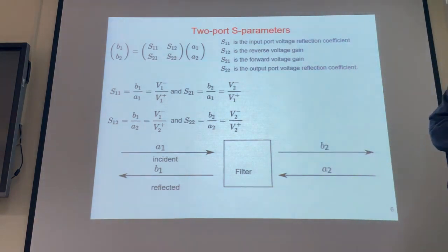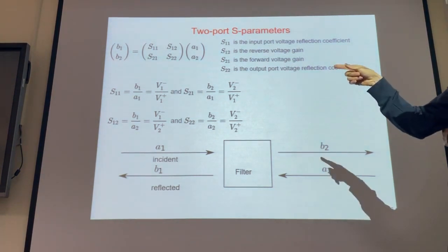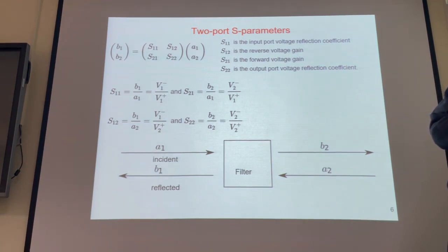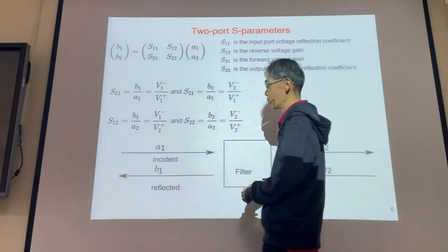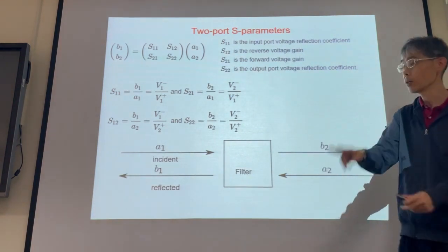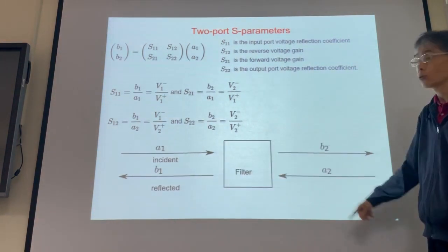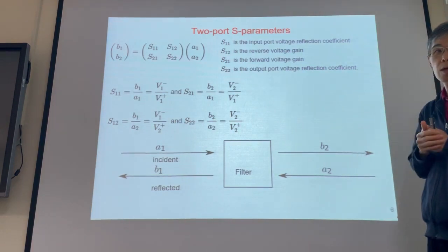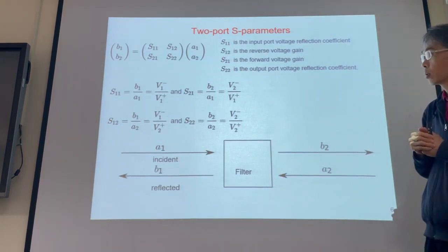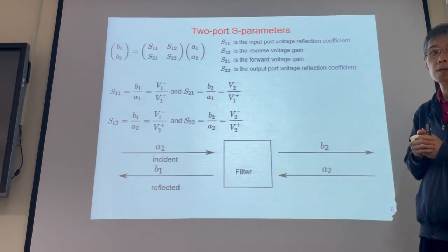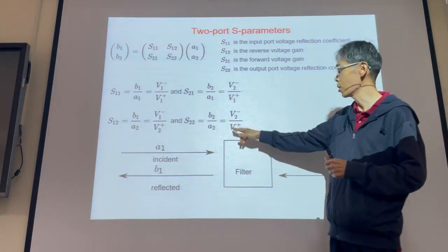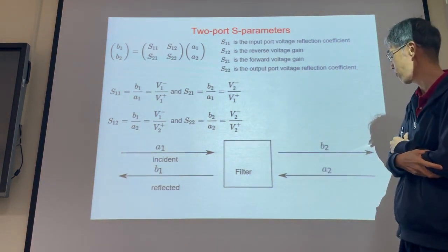V1 should be equal to S11A1 plus S12A2. Under which condition can we write V1 equal to S12A2? Here, S11 equals 0. In this system, we have two inputs only, A1 and A2. Yeah, A1 equal to 0. Okay, so for this, S22 equal to B2 divided by A2.